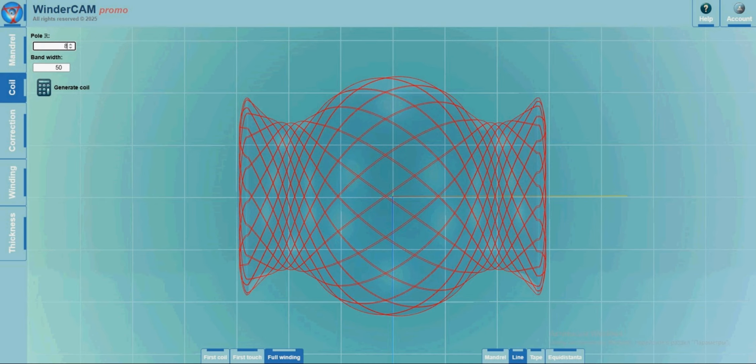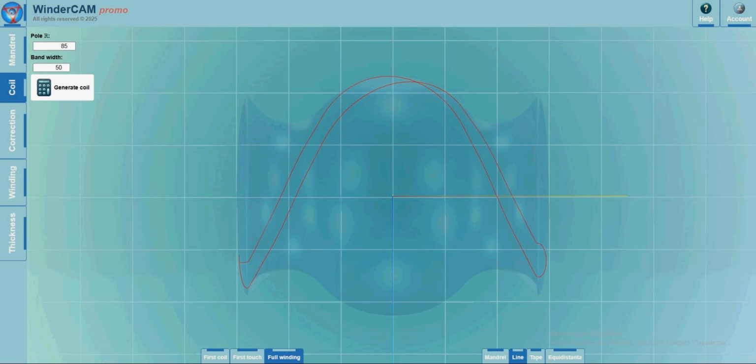This is an interesting case because it combines two different technologies, rubber processing and composite reinforcement. The compensator consists of alternating layers of uncured rubber tape and reinforcing cord mesh made from polymer strands. So it's like a hybrid structure.